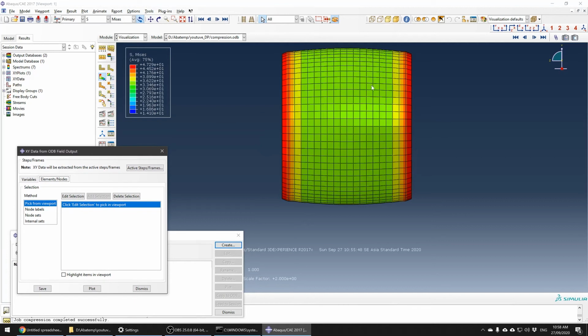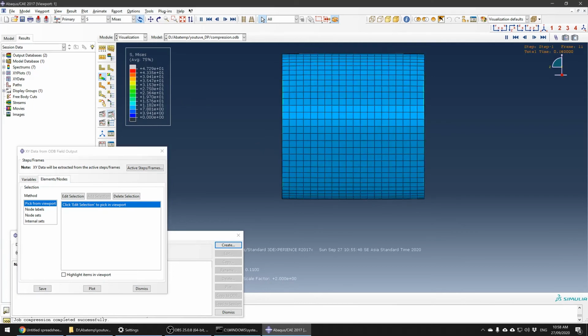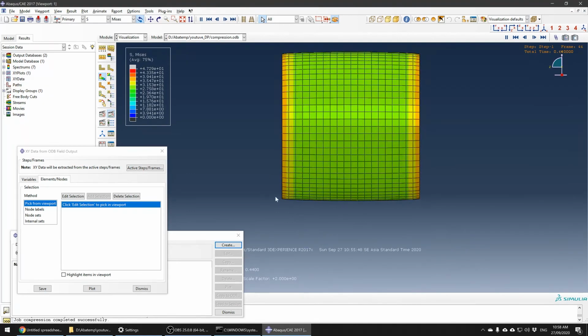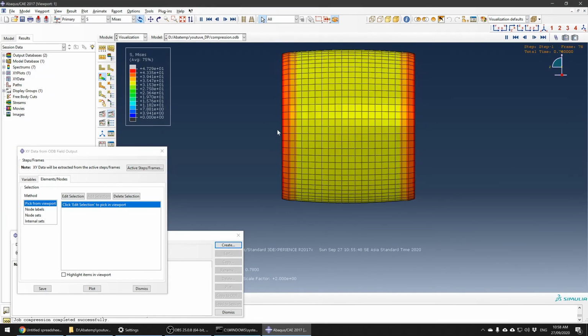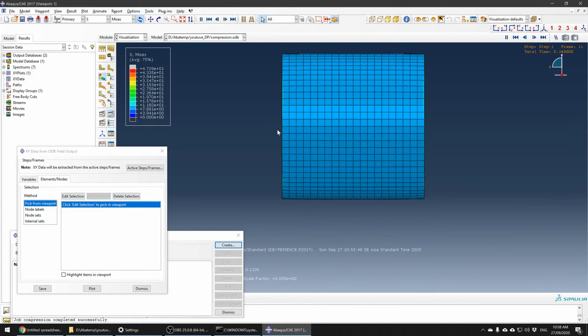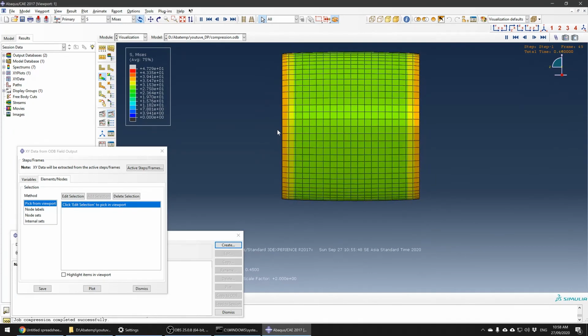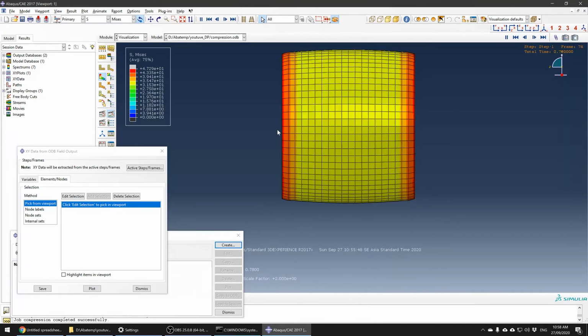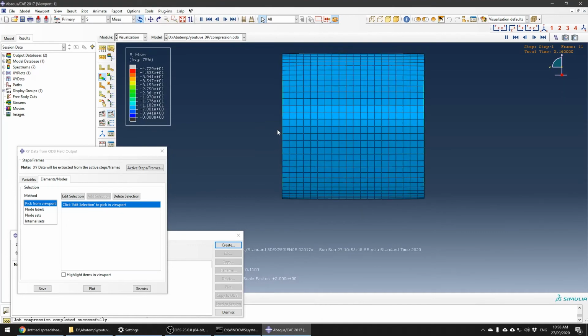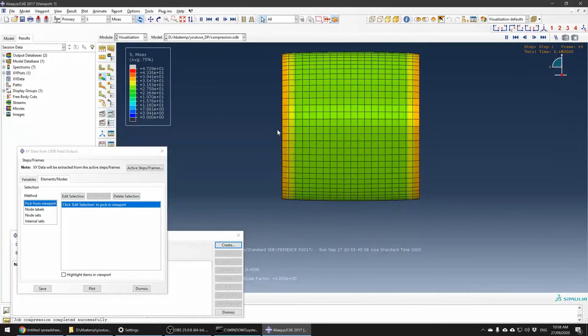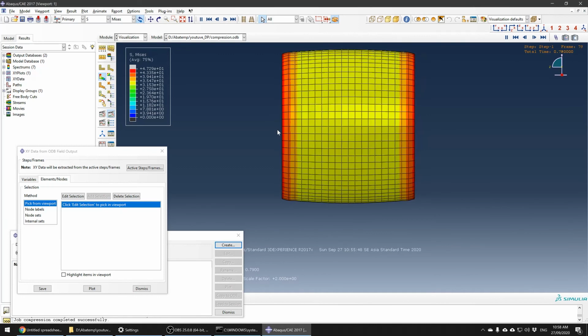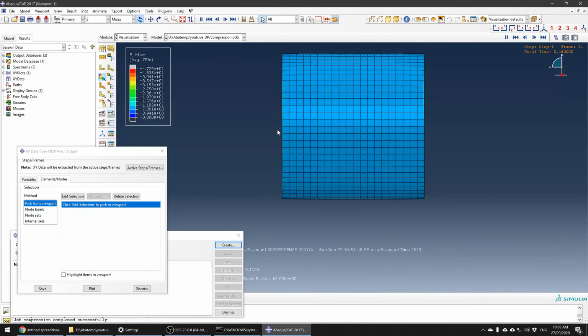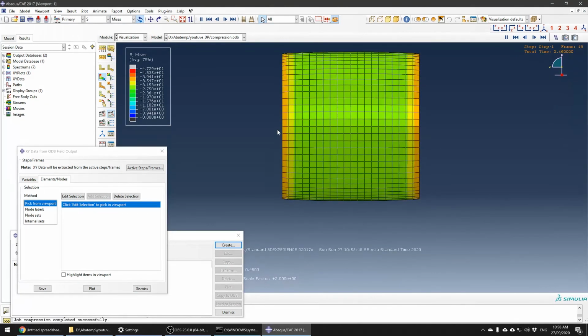So there's a barreling here. So this phenomenon called barreling: the diameter is getting bigger, especially in the center of the cylinder. This is very typical because here you fix the surface of the specimen. So during the split Hopkinson bar, this is the extreme case where we don't give the permission for the specimen to have this lateral expansion, right? So this is called confinement effect. So in real situation, it is not dominant like this.